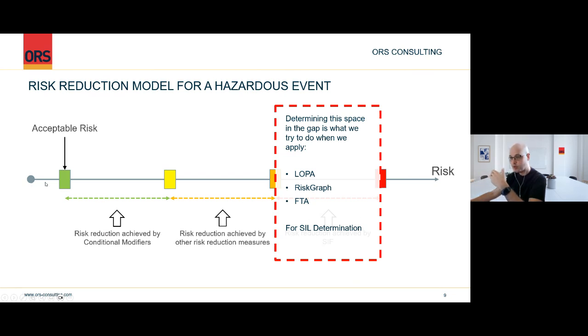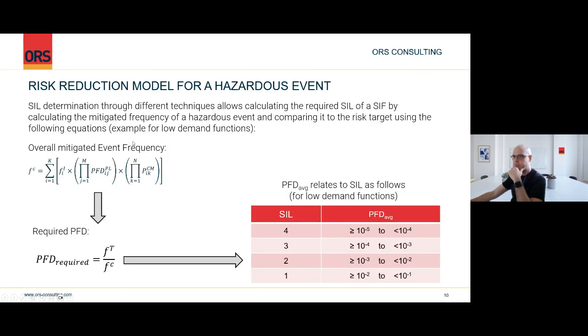And if you have a simple, unidimensional scenario, with maybe a few initiating events, but it's all very clear how the system is protected, what the source of the hazard is, and how to prevent that hazard from manifesting itself, then you can do that easily with a LOPA, for example, or with a risk graph. And then you don't need to do fault tree analysis, right?